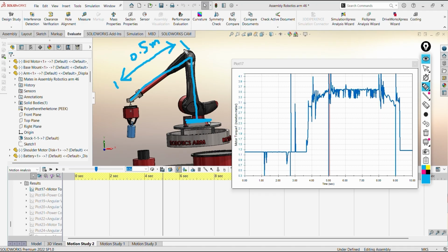Now we need to decide where this whole weight will lie. So in my calculation, I've approximated it to 60% of the arm length. So I have approximated that the whole weight is lying at 60% of the arm's length at this point. So here the 0.09 kg mass will apply. And here the mass of the jaw is acting, which is 0.29 kg. And for the aluminum block, it is 0.51 kg.